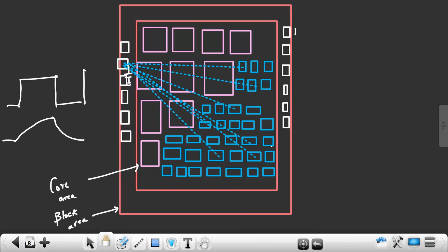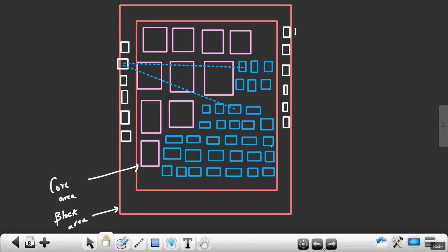So where is the square signal here? Where is the pulse width? This pulse width is lost. Because of the huge load, because one port is driving all the cells, that is not fair. So for that reason, we will split the load. We will take buffers. If this is a clock port, we will take the buffers and split the load like this.